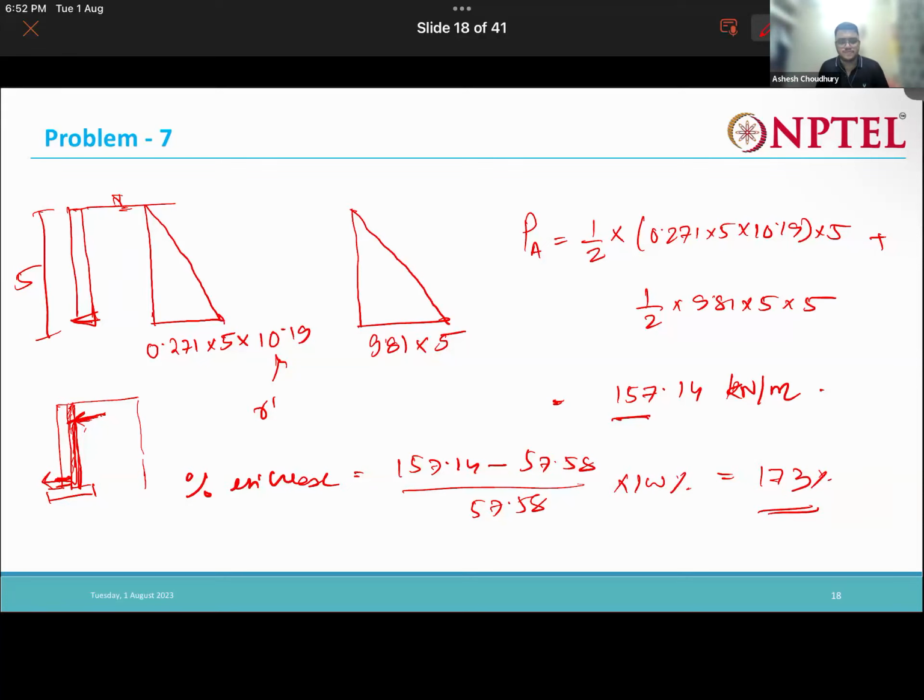So it's very important that when we construct a retaining wall, proper drainage has been taken care of. Else, whenever there is heavy rain and the soil gets submerged, there are chances that the retaining wall will collapse if we have not taken into consideration the high active thrust which gets generated due to the lateral thrust of the water.